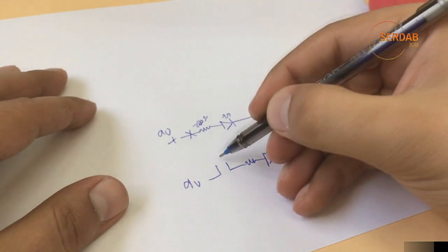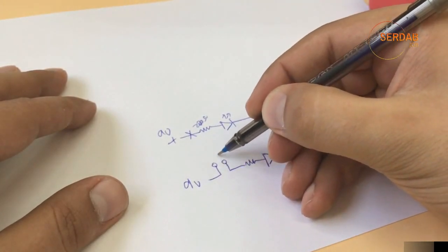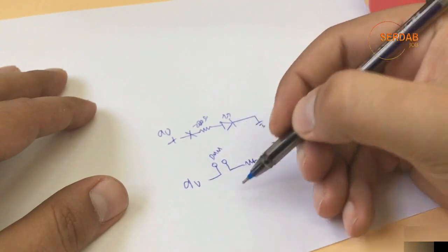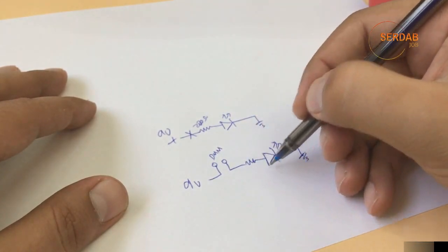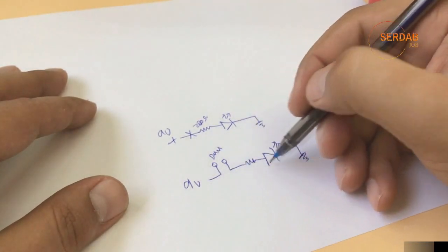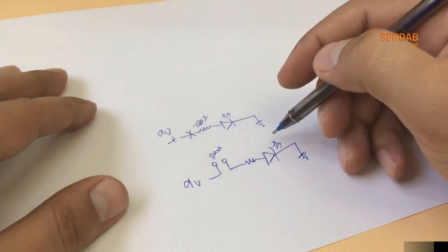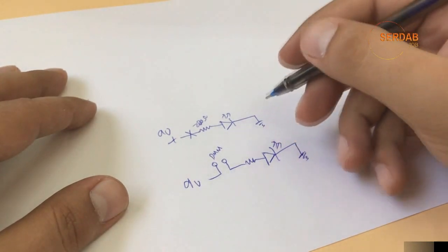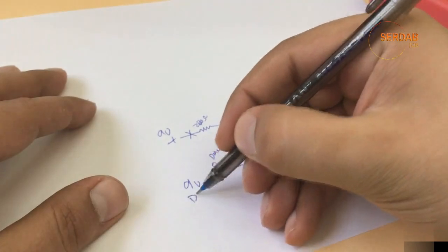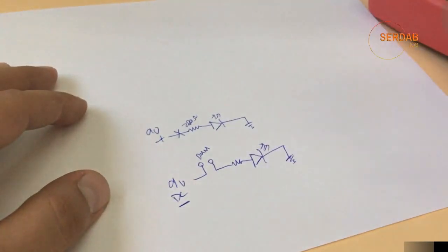And this. These are the two probes of the digital multimeter. We must add them in series with the circuit so that we can measure the current. Now, the same thing applies, as you can see, this is DC. The same thing applies for AC.